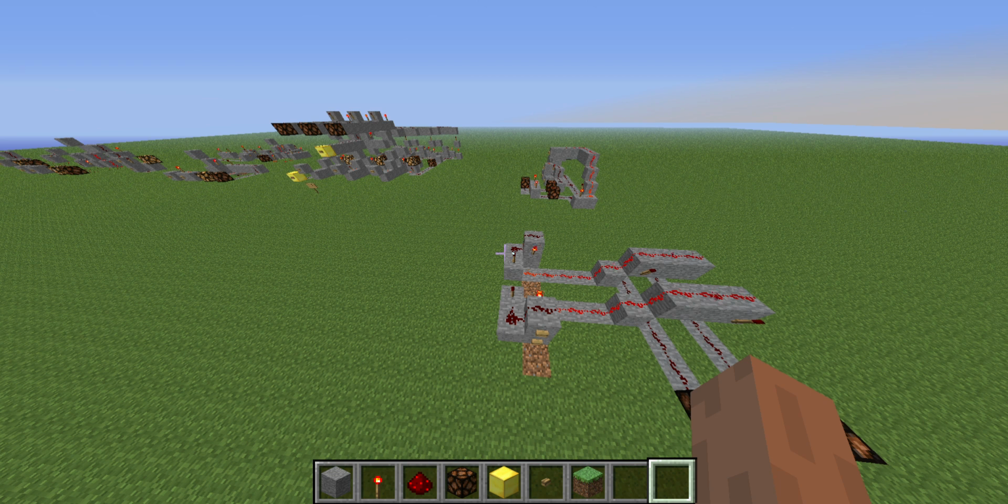Say, for example, a battery. Let's just say you want the rover to only come on whenever there's a... Let's just say you have a max battery that only has 2 volts. That's a rechargeable battery for 2 volts to turn everything on, okay? Let's just say now you want the rover to remember if it's at a certain percentage to deploy something, okay? What you could do is have an AND gate, or a data value, where it says basically if voltage is below, let's just say 1.5 volts, then trigger motor to deploy solar panels, okay?